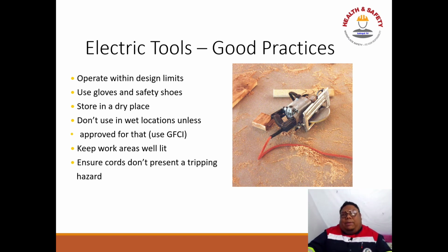Most safety officers fail the interview on this question only, guys. You must be familiar with it. Use a GFCI, a ground fault circuit interrupter. It is the same as an automatic switch relay: if it can sense a minimum level of amperes, it will trip off. The unit will trip off and no longer be used. It protects you from devastating electrocution.